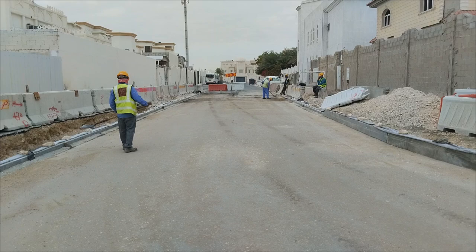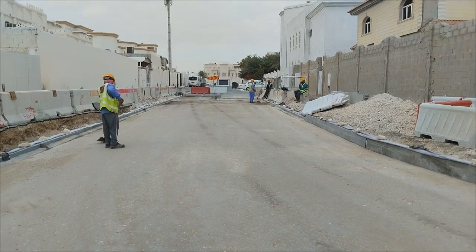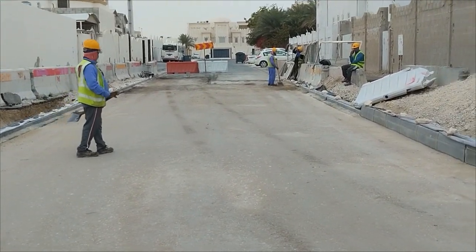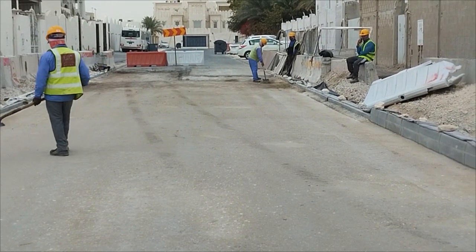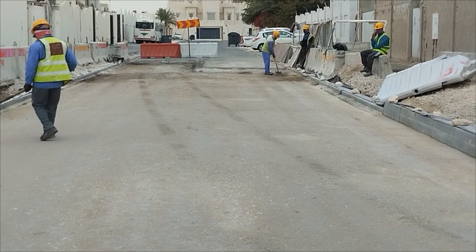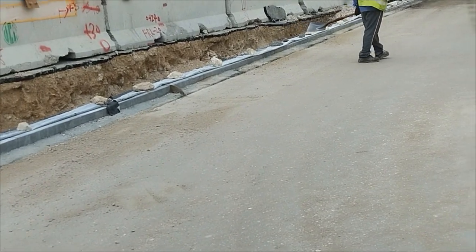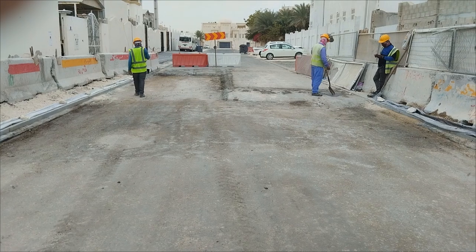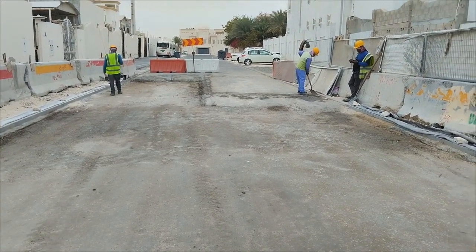During the compaction and the final inspection, the surface should be checked. There should be no over moisture area, no rubbish material, and no cracks on the surface. Then this will be acceptable for the final testing. As you can see here, some segregation was found, therefore some fine material is used to cover this area. The last point, the tie-in point, is almost completed.